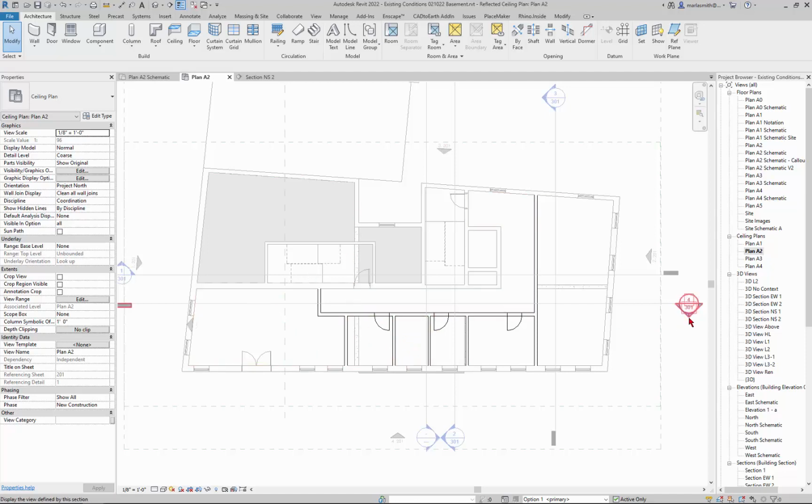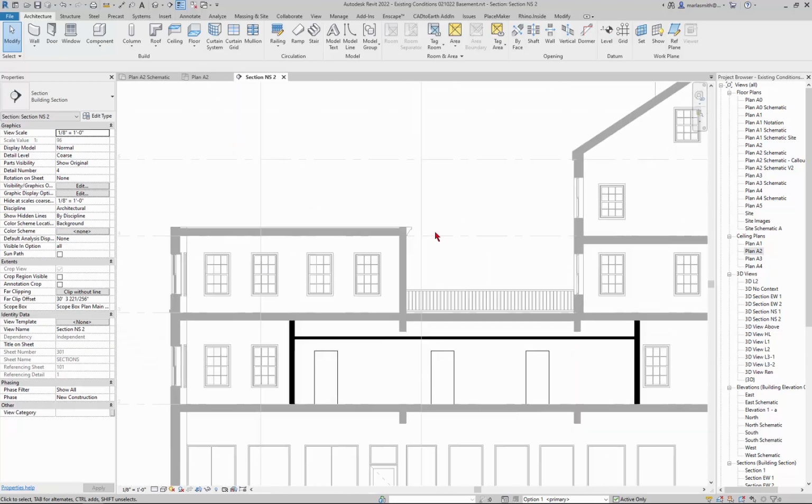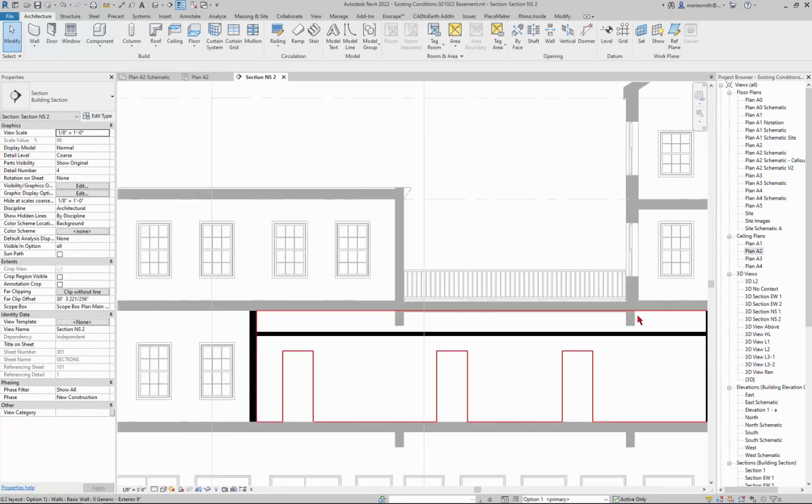So those are some of the considerations you're going to have to take into account. Like, how is the mechanical getting through there? Does it actually get dropped? Does some other sort of mitigating circumstance start to help out with that? 8 foot's pretty low. Or maybe the mechanical runs from some side vent or something like that. So that's just something you need to take into consideration.